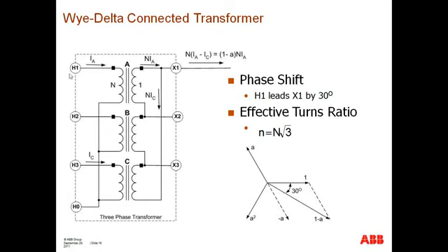And what I mean by that is, if you have a phase to ground fault on the Y side of this particular transformer, there will not be any zero sequence contribution from the X side winding of the system. The reason for that is because the zero sequence current will be trapped inside the delta and will circulate for the duration of the fault. So again, it provides a means to separate the zero sequence networks between two systems.